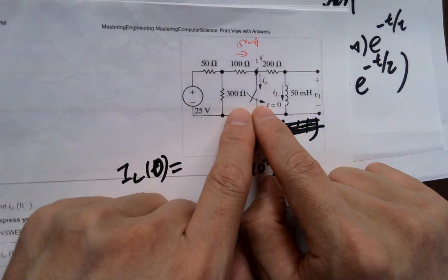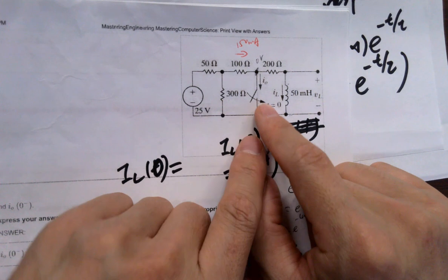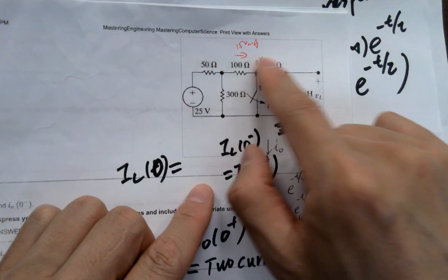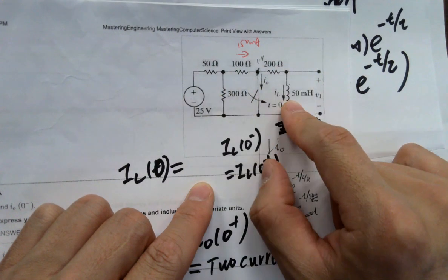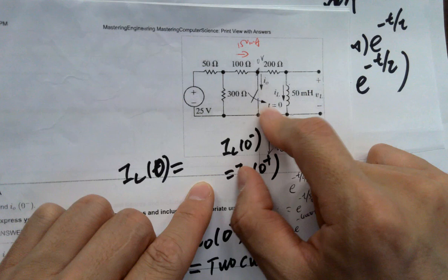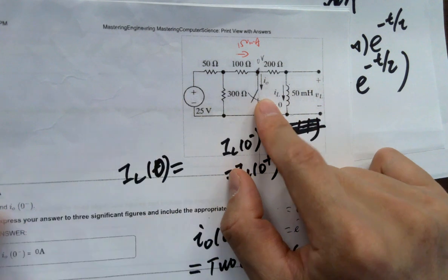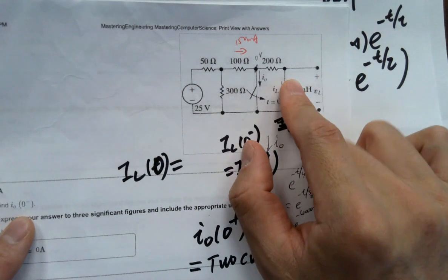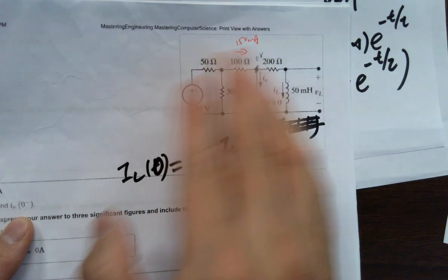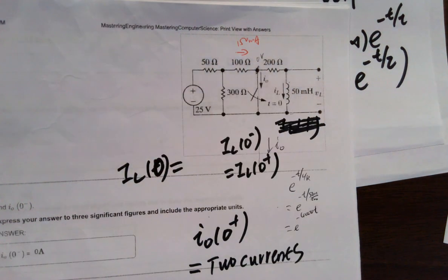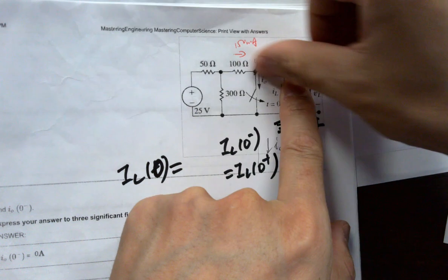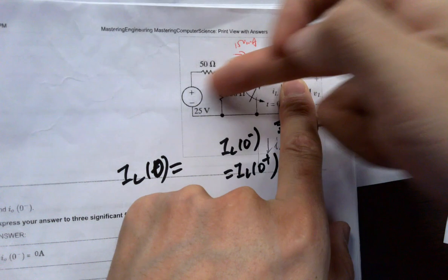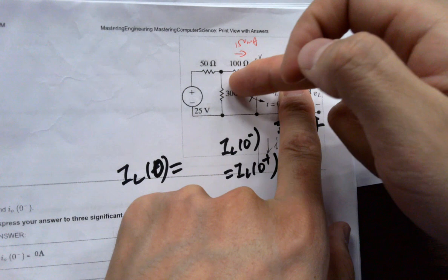Okay, so at time 0 the switch is getting closed. Before time 0 it is open, so it's charging up this element, and this becomes a wire because the current flows through it. Whenever this is closed, what's happening? This will discharge across the rest of the circuit. So you have to look backwards to find the equivalent R, so you can find the tau, the time constant, right?